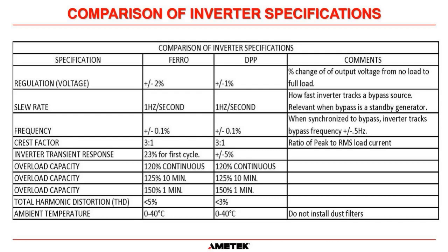Do the electrolytic caps like it? No, but we put them in there so that they can run for the specified 10-year life of electrolytic capacitors. That's the main thing of temperature. The electrolytic capacitors in the machines are affected by temperature.